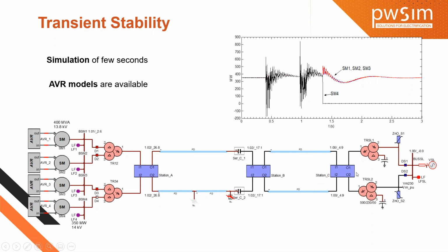The equivalent impedance of the generating stations is added here. By using the EMTP software, we are creating a fault on the second transmission line, and we are opening the breaker, again reclosing the breaker, again opening the breaker. A lot of times we are opening and reclosing the breaker, and finally we are opening the main breaker of the synchronous machine connected to the transmission line.